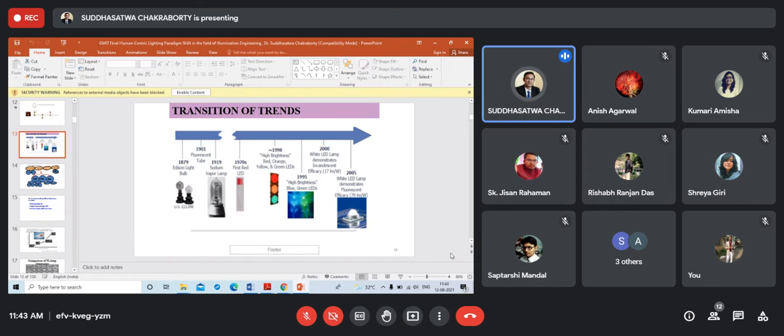So this is basically the diversification from conventional sources to LEDs. But to make it that, the light is required to be distributed. Last semester, we talked a lot about distribution and different photometric parameters like the polar curve, the Cartesian curve, and the gonio-photometers. Here we will also be talking about the LED, but we should ensure that the LED distributes the light. But for indication lamps, mostly traffic signal lamps, we don't need that. It's a very concentrated beam.